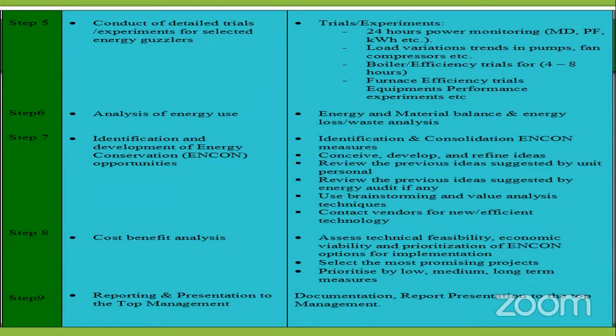So make a point that auditing is being done for the entire house or building, where the lighting load is separated with a line diagram. Then the heavy loads are separated in a separate line. And then third, what could be the efficiency improvement on such parameters? Like, if an incandescent lamp is there, change it to LED bulbs so that it would be an opportunity to save energy. Then going forward, we can also look at the distribution systems, whether earthing and other things are proper or not. So we need to have a benchmarking. So that is going to be there.